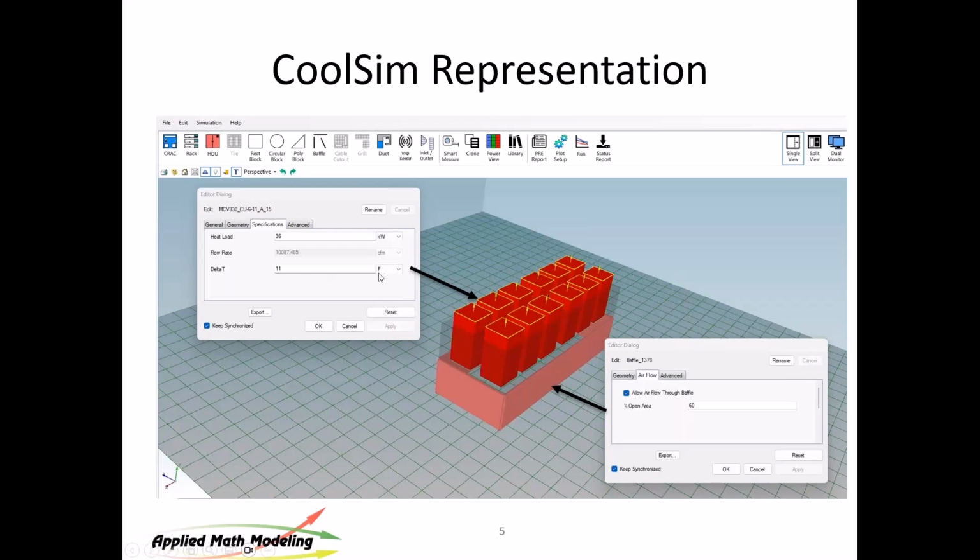They'll also give you mass flow rate. If they give you maximum mass flow rate for the whole set, then of course divide it by 8, give it to each one of them. They may give you delta T. If not, wiggle the delta T until you get the mass flow rate to where you want it. This is not an unusual delta T for these devices, 11 degrees. I'd like to see higher, but that's not an unusual number.